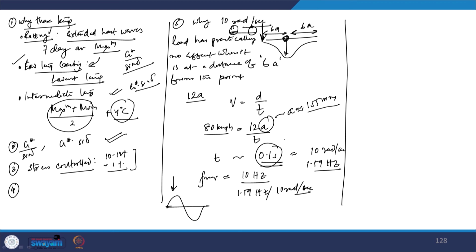Now talking about the specifications, let us talk about the 1 kilopascal specification. As I told you, for the development of the SHRP specification, a special task group was formed by FHWA, and the specification limits were decided based on consensus by the expert task group. It is very interesting to note that even this specification has been derived from the viscosity grading system.